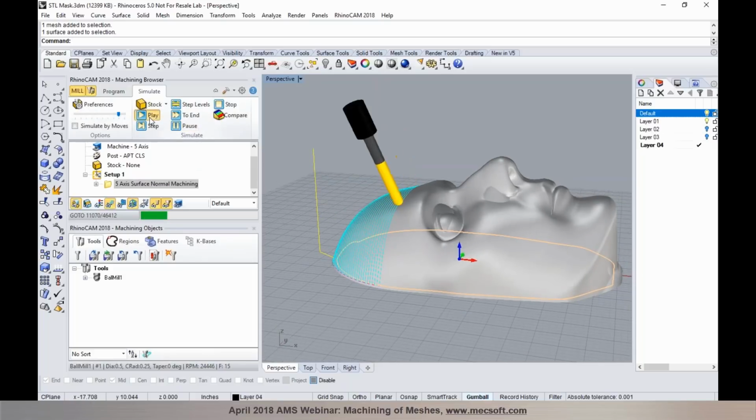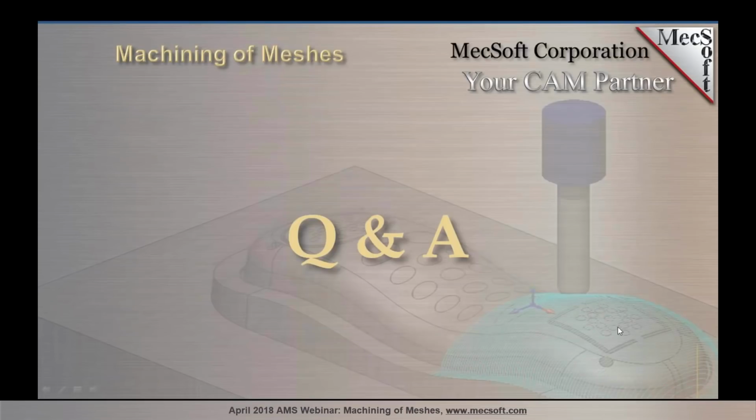There was one question about whether we can convert meshes to NURBS. We don't do that. We stop at the mesh production and all the mesh tools that Uday showed you. And you will have to use the Rhino tools for it or use some other product or plugin. I believe Rhino has a few plugins that can take the mesh data and convert them to NURBS.